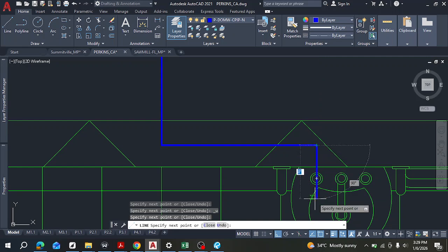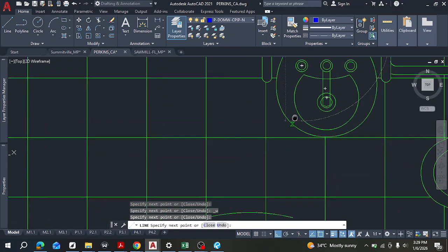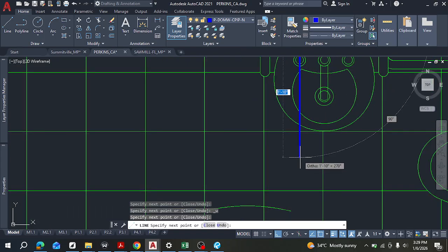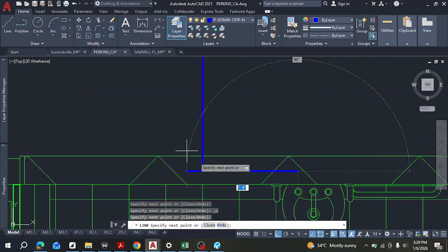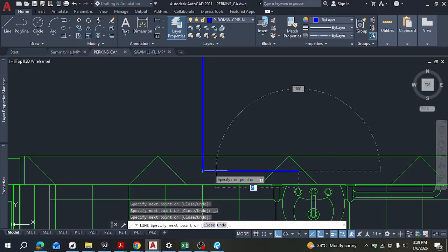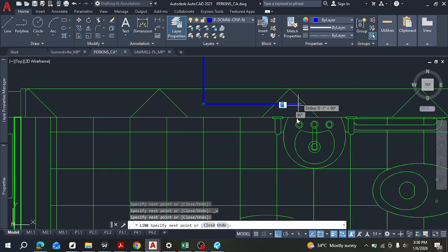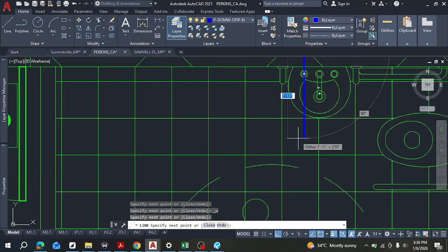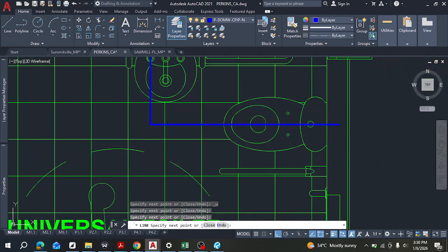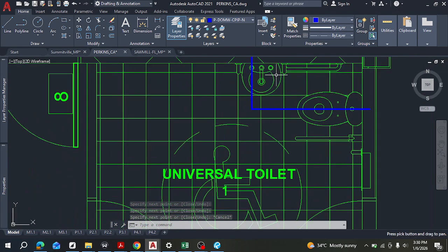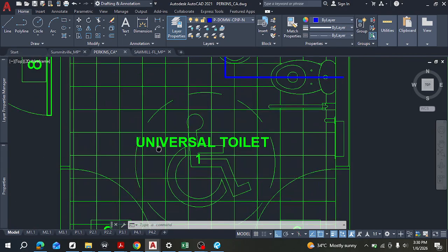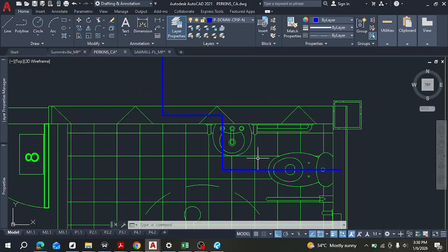Now that is called snapping. That is snapping because I just hover the cursor and then it snapped to the point I wanted. So at this point it entered from the ground into the wall. This is an exterior wall. In this case, you don't have a choice but to use an exterior wall, and then it goes up into the ceiling, and it continues in the ceiling and I drop it here finally, because this is all that I think needs water. If I had other fixtures, I would have continued the routing, but this is where it ends. It's a very small project.